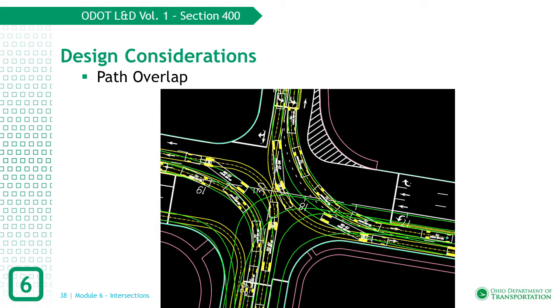Here's an example of what to watch for when establishing the stop bar locations. Notice the southbound to eastbound dual left turn movement in this image. This was designed using a WB62 truck on the outside with a single unit truck on the inside. Notice how staggered the southbound left turn lane's stop bar is relative to the through right stop bar.